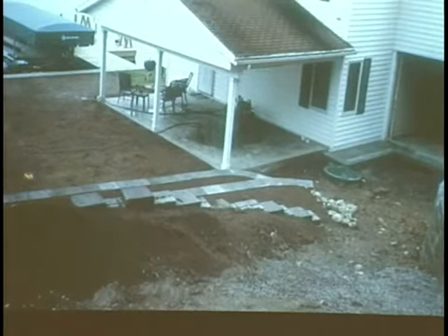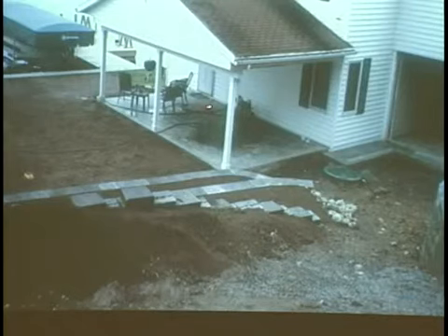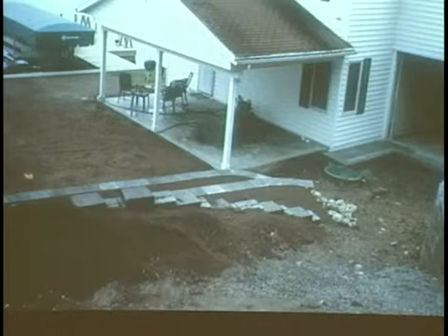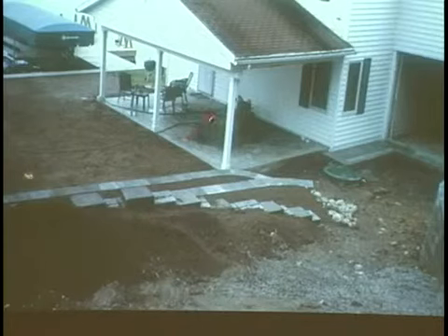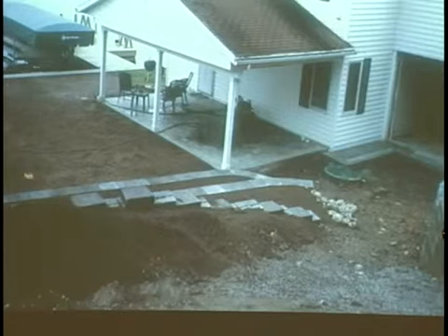Here's a situation which, prior to DEC, this area got filled in and this place got built back in the 50s, 60s, who knows. They had a steel septic tank here, leach lines in the fill area. The steel septic tank rusted out, caved in. The guy said, well, we'll just set a new septic tank here and tie in. I said, you're in a fill area here, you've got the lake right here. Our policy is, for a failed system, the repair is going to meet the current health department standards as best as possible.